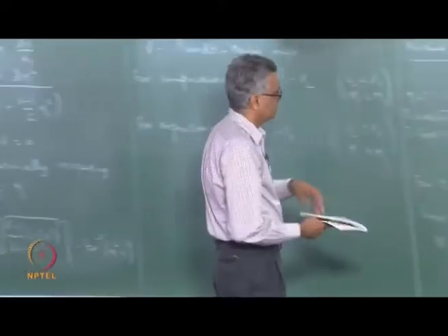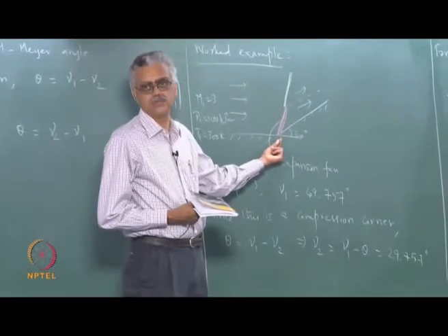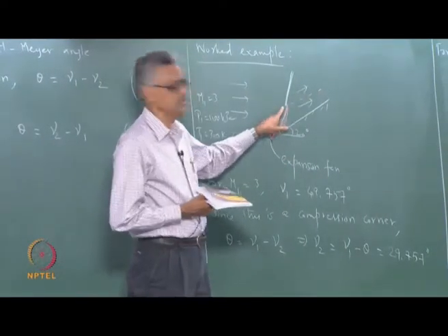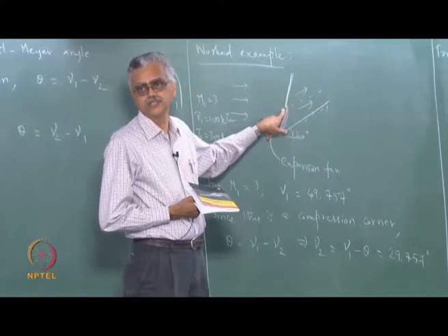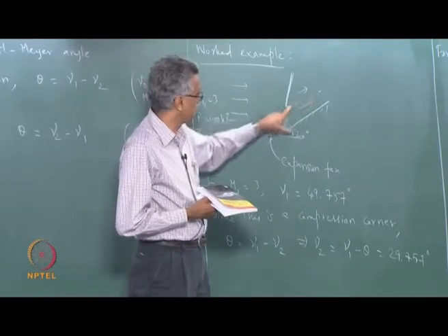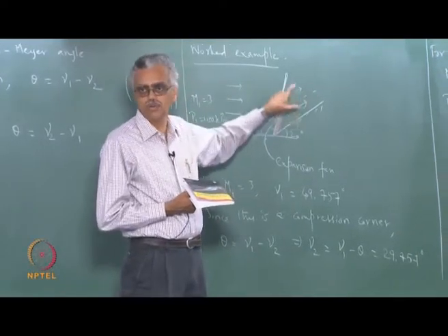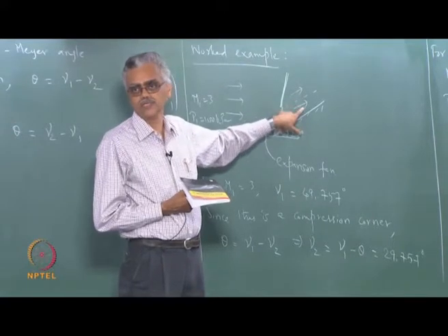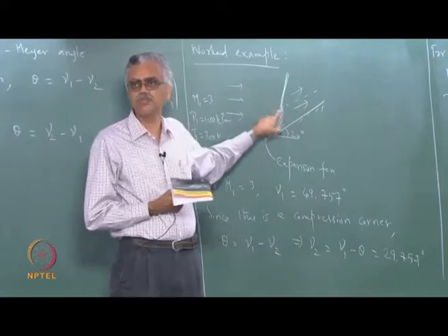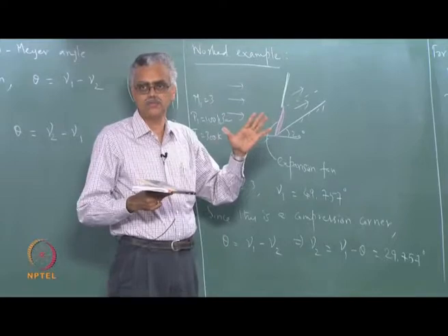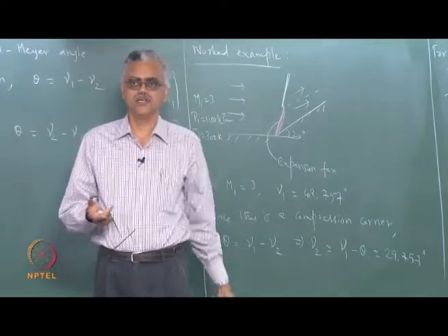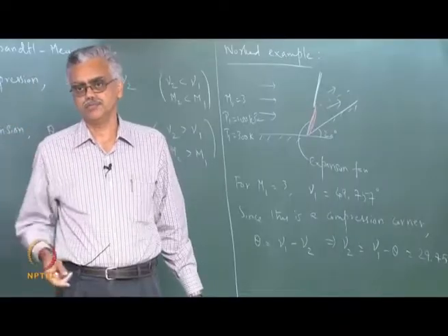No, the thing is, as you bring this closer and closer, you are going to have a complex interaction in this region. The slip line itself may not be just a slip line. So, to equalize the pressure here, you can have, for example, an expansion fan which originates from the corner here and then goes out. Slip line need not be just a discontinuity. Slip line can also create additional flow structures to equilibrate the pressure.